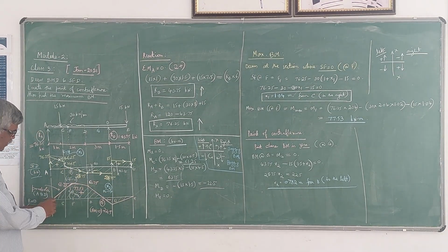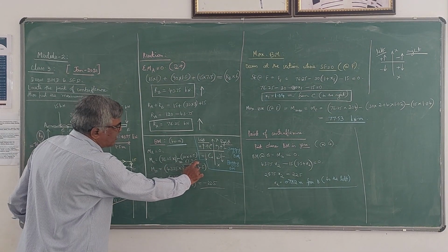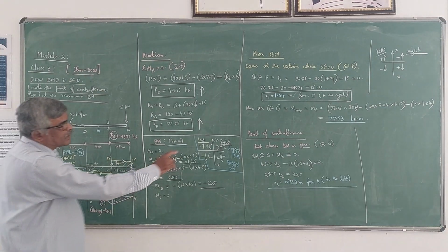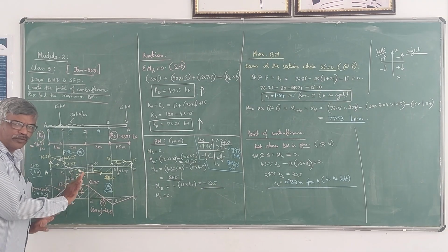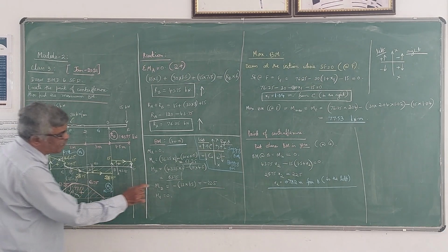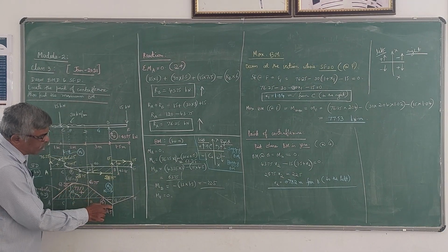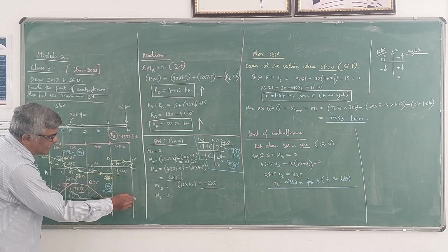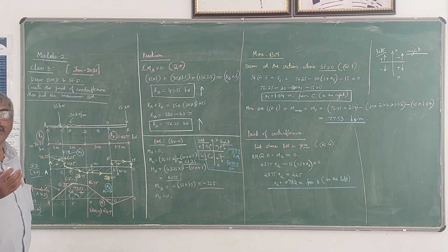Now at A the bending moment is 0. Next point is C. At C it is 61.25 kN. Then at F it is 77.53, slightly above that we have to show. It need not be scaled, but you have to write the values. Then at D it is 63.75, it decreases from F to D. Then at B it is negative 22.5, you have to show below the line. Then at E it is 0. So locate all these points, and then how to join them.